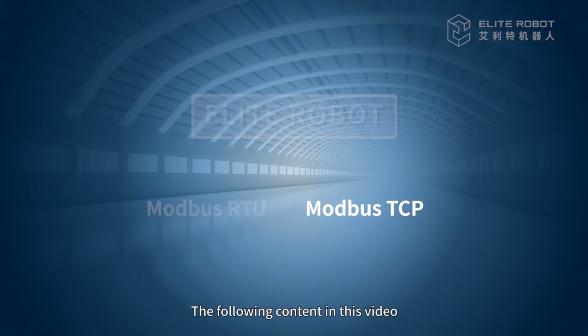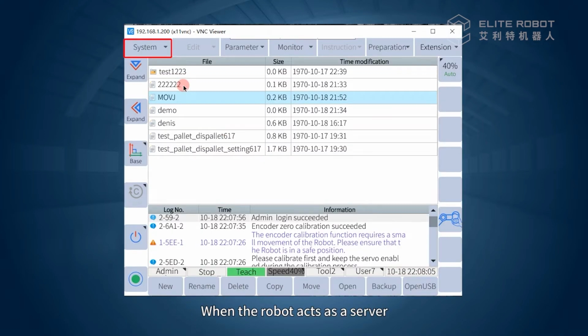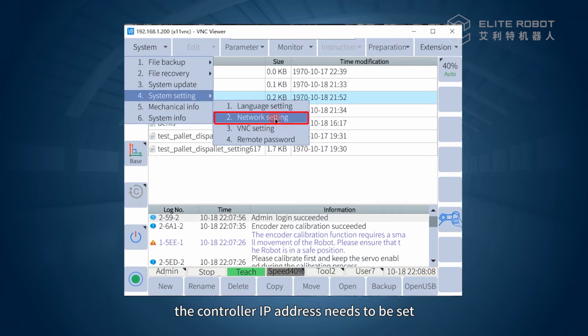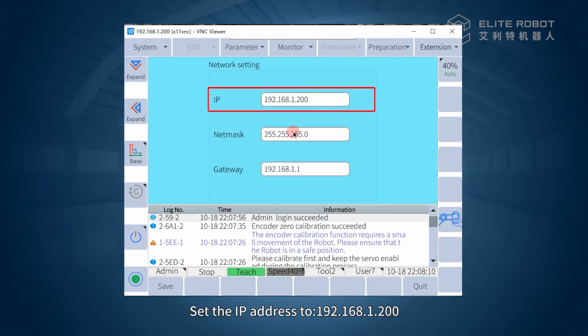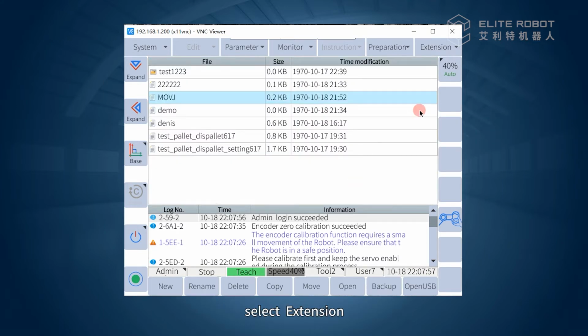The following content in this video will use Modbus TCP as an example to explain the configuration on the Elite Robot. When the robot acts as a server, the controller IP address needs to be set. Set the IP address to 192.168.1.200. Set the subnet mask to 255.255.255.0. Next, select extension, Modbus Slave.